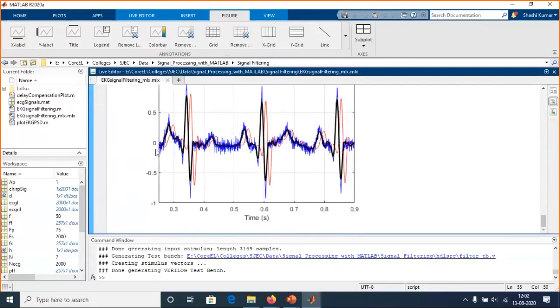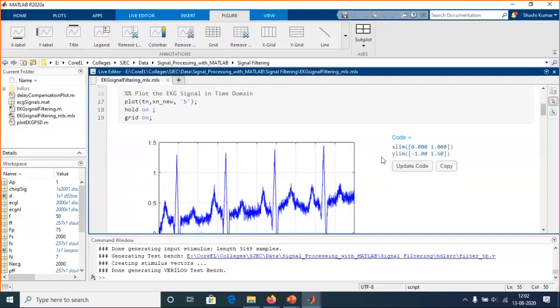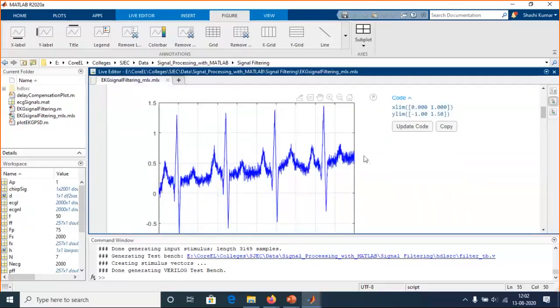When it comes to analysis of an ECG signal, you usually take care of the PQRST components and the distances between them, like PQ and RS, and many other things. When analyzing a biomedical signal, you can do this analysis very easily now because you have the completely pre-processed signal, and visually you can see that you can extract many features from it. Compared with the signal we had at first, where we wouldn't be able to make any sense of the input, once we filter and compensate for the delay, we can extract good features from this.